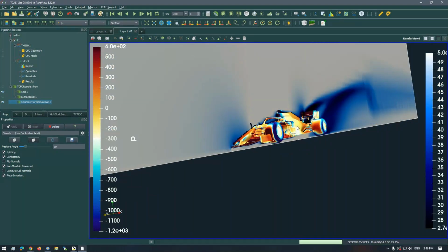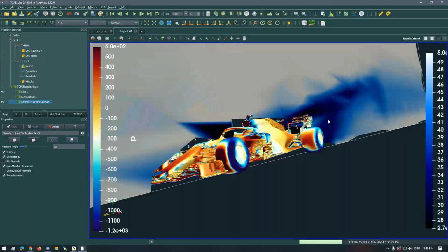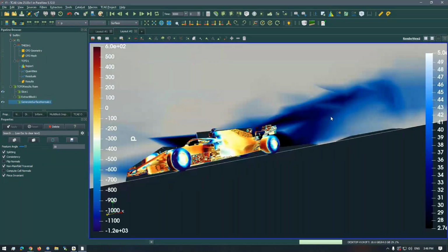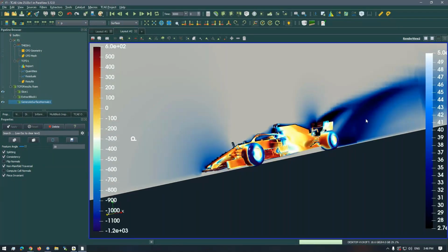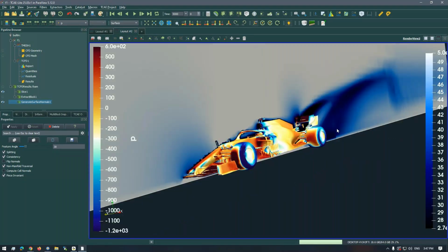Then you can check, for example, the effect of your turbulence model and the mesh. Of course, the mesh is very important. It's always an iterative process, right? In this way you can go into more and more detail to check what needs to be checked to achieve the given accuracy.